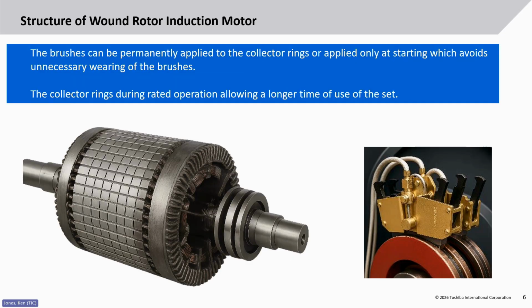So this just shows a single connection on the slip ring itself, but the design characteristics associated with the rotor and rotor assembly means it will handle very high difficult loads with a lot of kVA demand. And so you're looking at a winding that's internal to the rotor, three-phase, that is configured such that it handles high torque and high load characteristics.